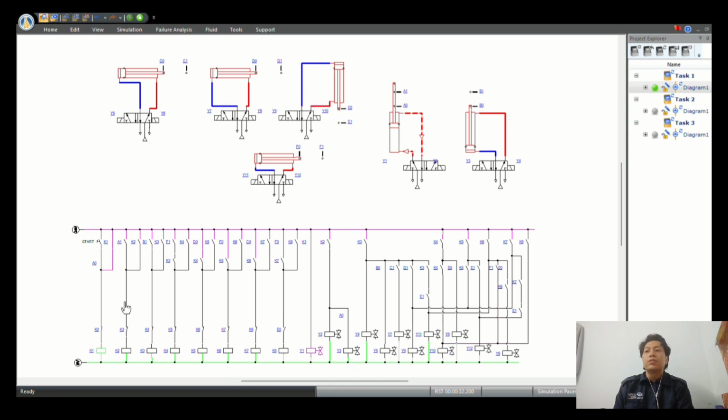Once the limit switch A0 is reached, solenoid Y3 advances cylinder B. At the limit switch B1, relay K3 will energize the solenoid Y4 to retract the cylinder B. So when relay K3 and limit switch B0 are triggered, solenoid Y5 is active.